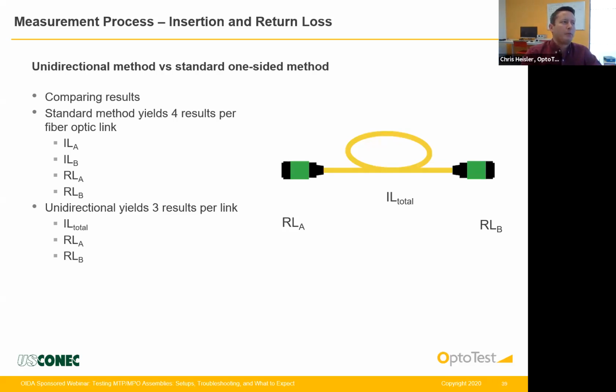So there's been some guidance on that testing, and the IEC has started talking about how to handle some of that, and the TIA will be discussing this type of application this week, I think either tomorrow or Thursday. What's suggested is using a receive cable on the backside of the bend-insensitive multi-mode assembly. With bend-insensitive fiber, the leaky modes or lossy modes of the fiber don't dissipate very well with length. So on short assemblies, those leaky and lossy modes will continue down the fiber and be coupled to the power meter.